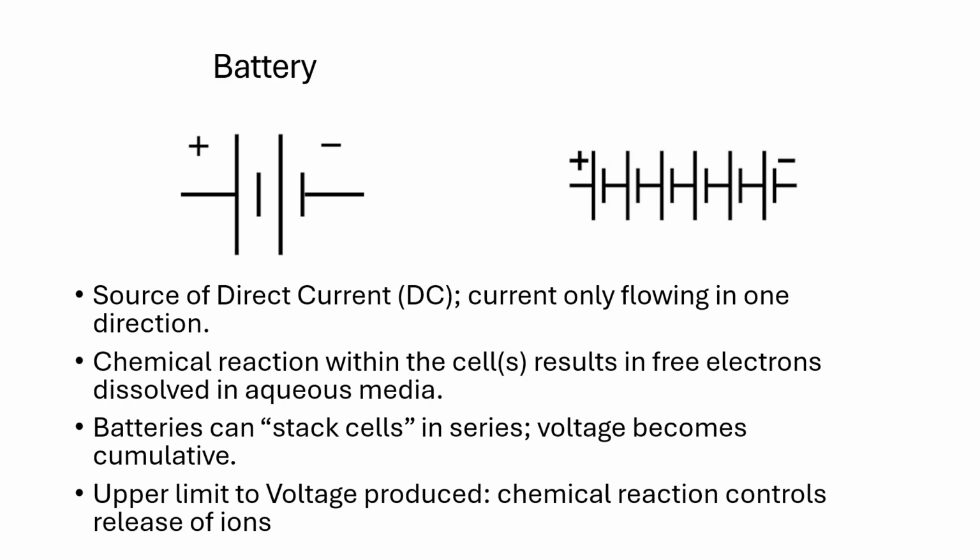The voltaic pile, you can make one at home. You just need some vinegar, some zinc plates, and some tin or copper plates. You stack the plates in alternating elements, so tin, then pour some vinegar down, then some copper, and then pour some vinegar down. If you put it in a bucket and submerge the whole thing in vinegar, that works the best. Connect one wire to the tin plate at the bottom of the stack. Connect the other wire to the copper plate at the top of the stack.